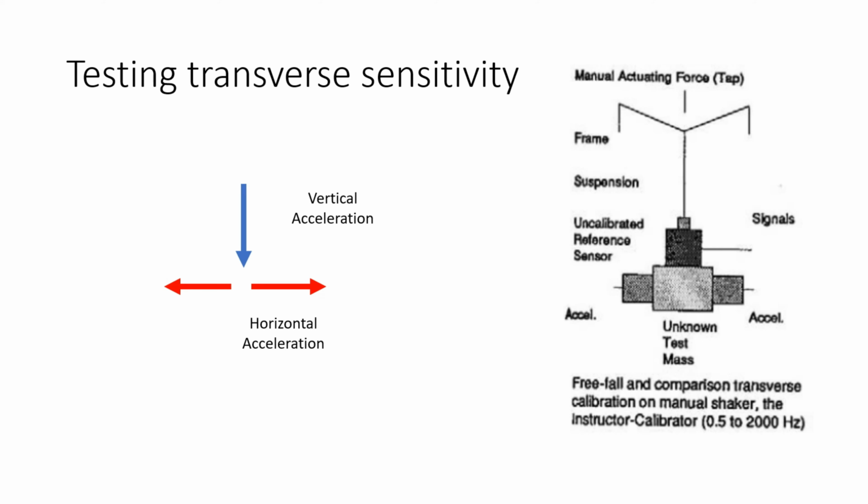Here we're going to have an experimental setup with 3 accelerometers, number 1, 2, and 3, with the third one measuring in the vertical direction and the first 2 measuring in the horizontal direction. Now we get the voltage values for V1 and V2, and we average the two, which results in their longitudinal acceleration measurements being canceled out.